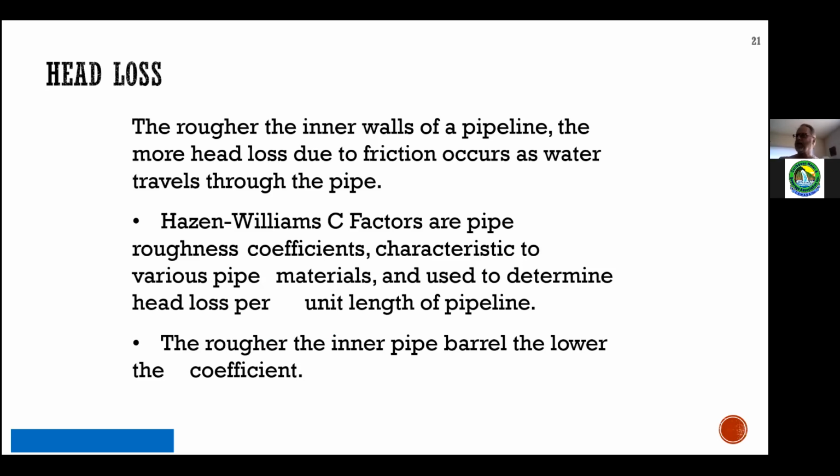When you look down the barrel of a pipe, say a 2-inch galvanized pipe that's been in service for 40 years, you're not expecting to see a smooth pipe wall. You'll see iron deposits and tuberculation, maybe some sediment. And now that 2-inch pipe is actually behaving as if it was a 3/4-inch pipe.